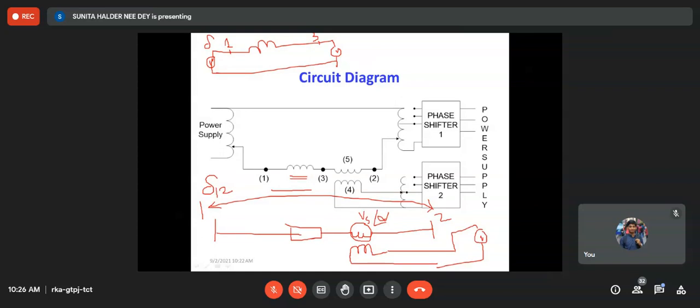Because in a practical power system, when there is a load, that creates the loading of the generator, and when we supply the prime mover input, the load angle is created. In that way power transfer takes place. But there is no provision of that in the laboratory, so we have to simulate all these things. That's why a phase shifter is required. I hope you have understood.